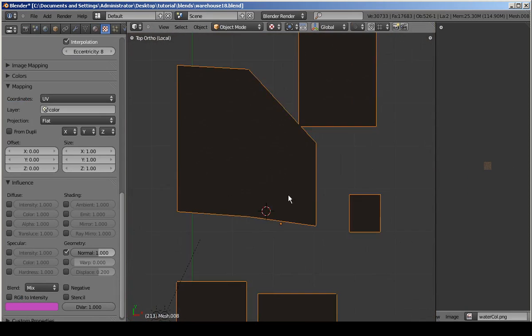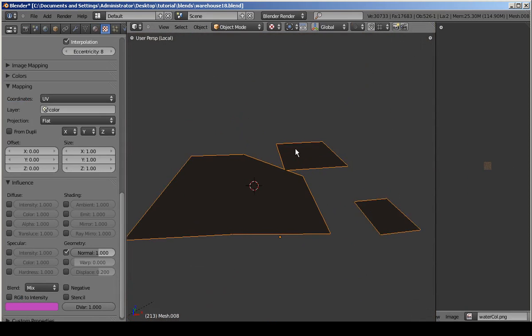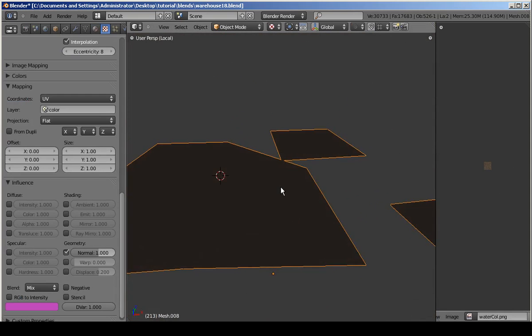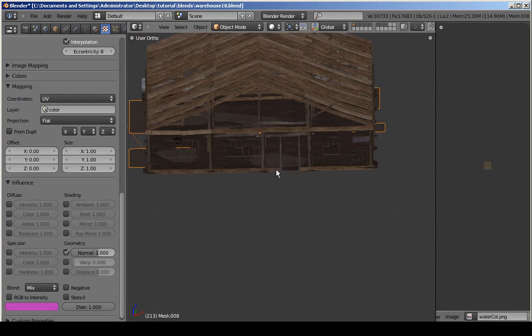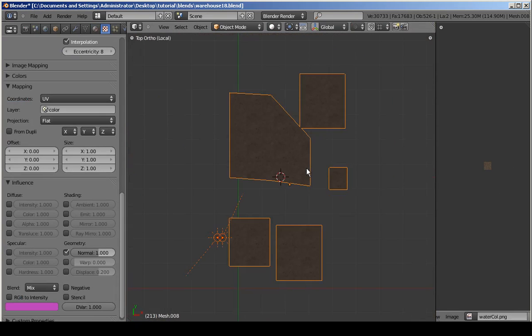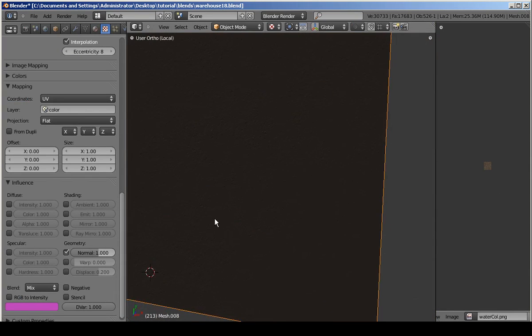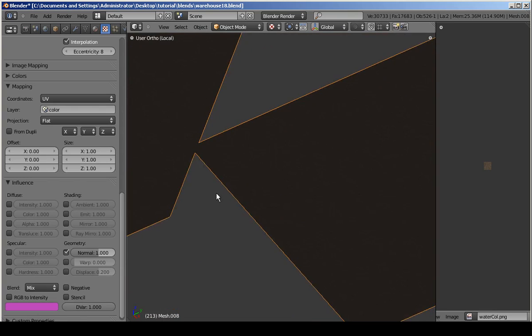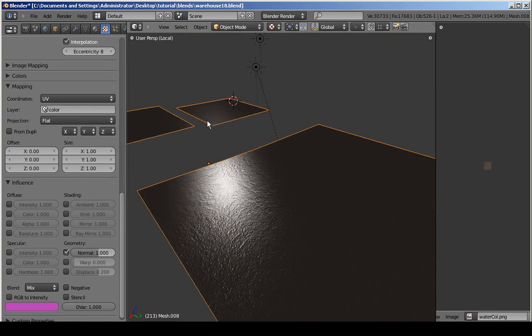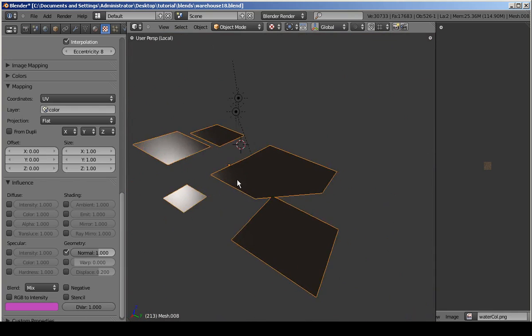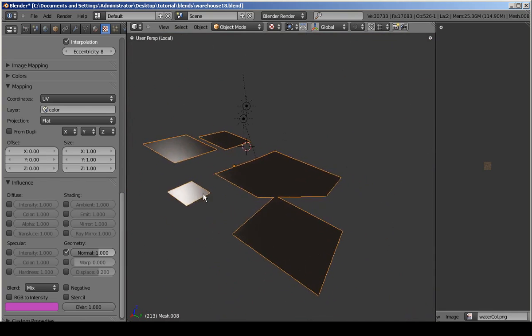So now I took the puddles and the lights into the local view. I took the lights too, just so that everything wasn't black. So now I'm just going to take the one puddle that actually has a normal map displaying correctly, and I'm going to replace those other puddles that are very flat shaded and don't have the normal map.